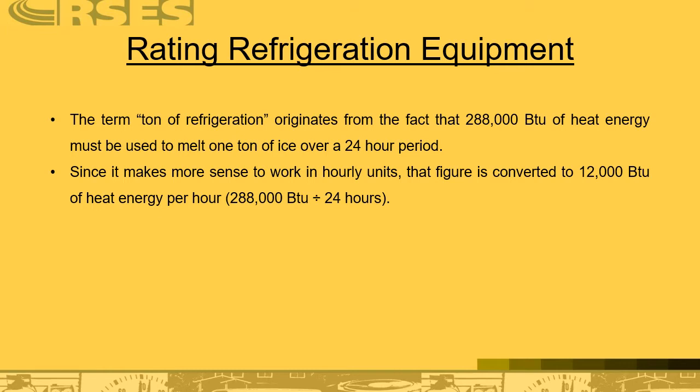It's very important when you're purchasing air conditioning equipment that you look at the heat gains and heat losses in each area of the house. As an example, room air conditioners are also sold in BTU ratings, and it can be 6,000, 9,000, 12,000, 18,000, 24,000, etc. Now, if you buy a small unit and you're trying to cool off a room with a high ceiling and you have 5 or 10 people, a 6,000 BTU unit is not going to cut the mustard under any circumstance. It's extremely important you calculate how much heat is being generated in the room on the hottest day of the year.